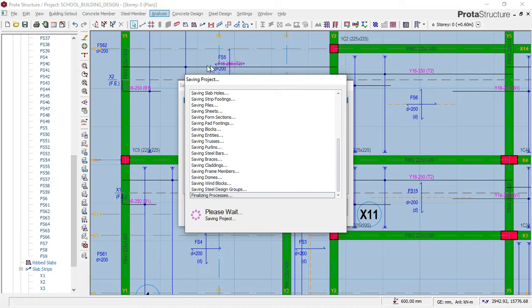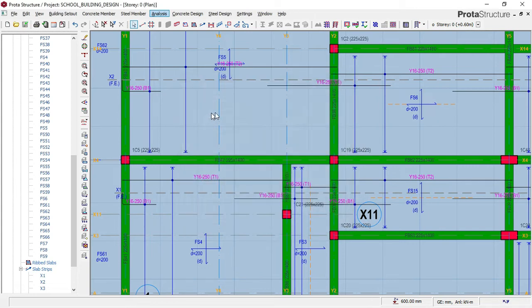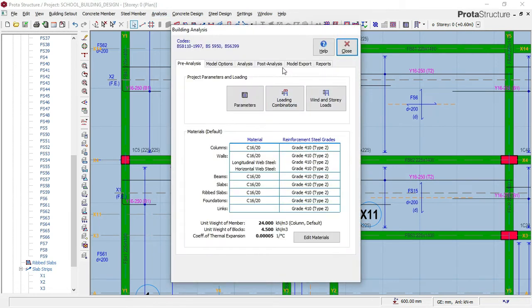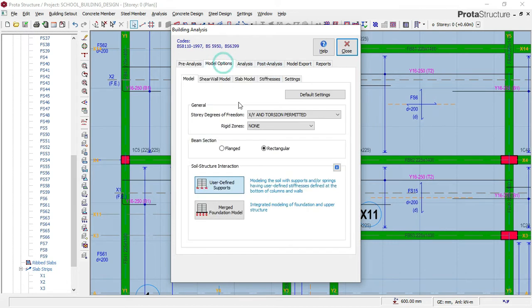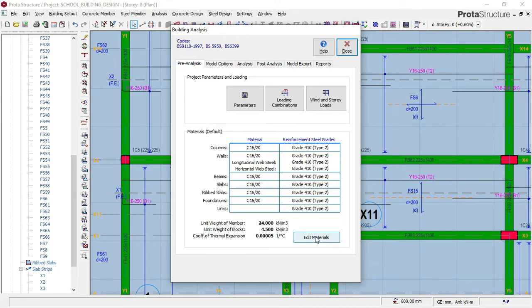So if you compare it to your slab table, you will see that it is falling directly on the Y16. But let's see first if we assigned the foundation to use Y16 alone and not Y12. Okay, let this stage just pass, and then we'll go and check that right now. So we go to this place right now. Let me see, sorry, on here, and then go to edit material, and then go to foundation floors.